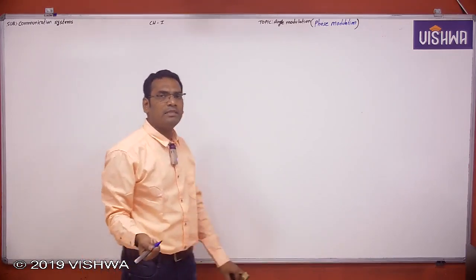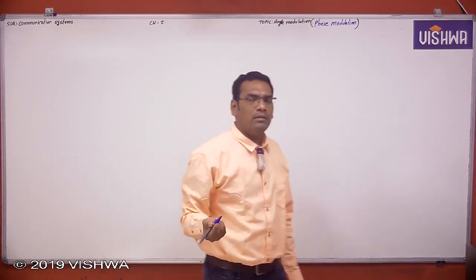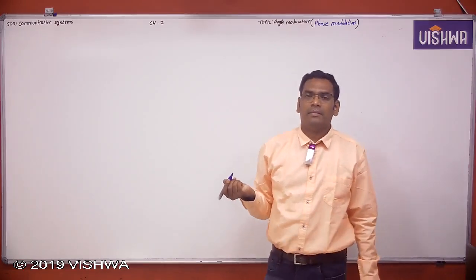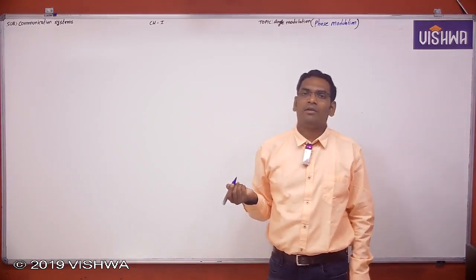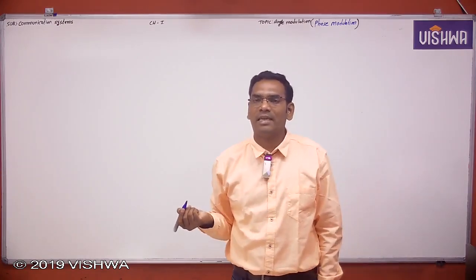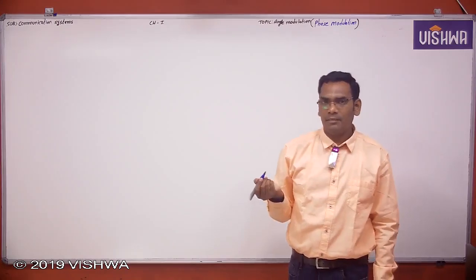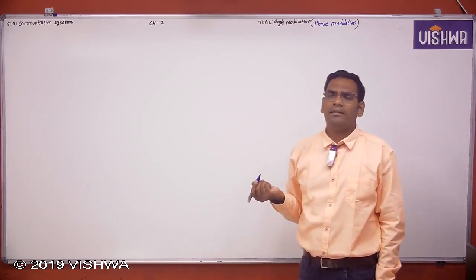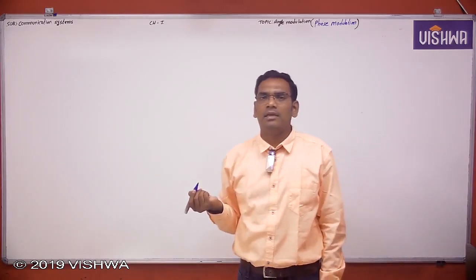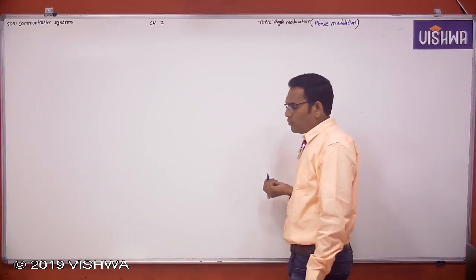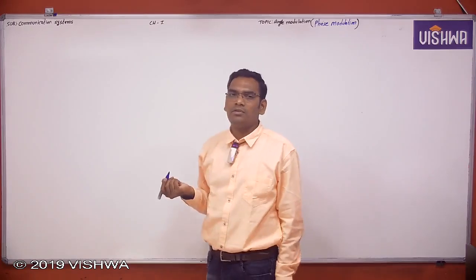Now, phase modulation. What is the definition of phase modulation? First you tell me. The instantaneous phase of the carrier is changed in accordance with the amplitude of the message signal. Everywhere the amplitude of the message signal is changing, the phase is changing. The phase of the carrier before modulation and after modulation is not the same.